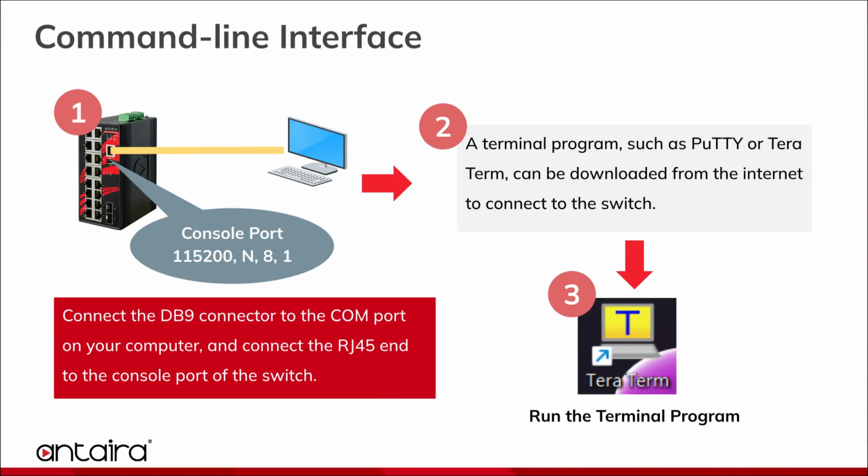Antaira Ethernet switches support CLI management. You can use either the console or Telnet to manage the switch via CLI. Before configuring the RS-232 serial console, connect the DB9 connector to the COM port on your computer and the RJ45 end to the console port of the switch.